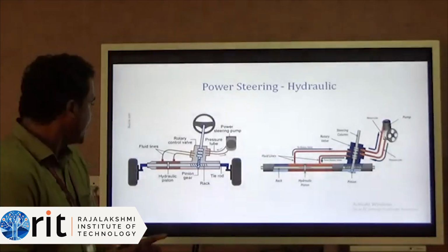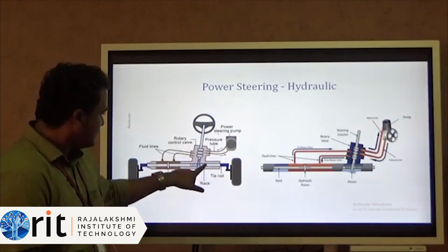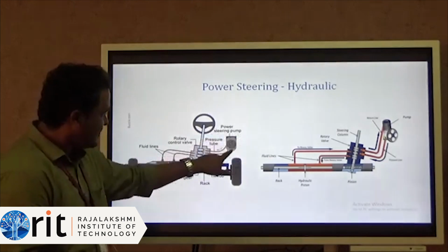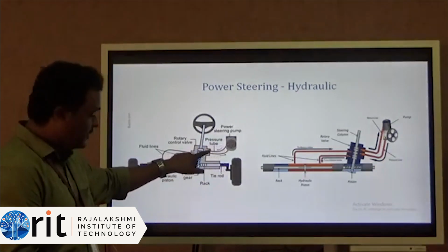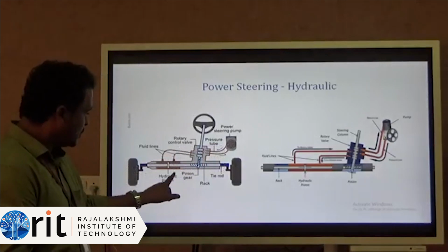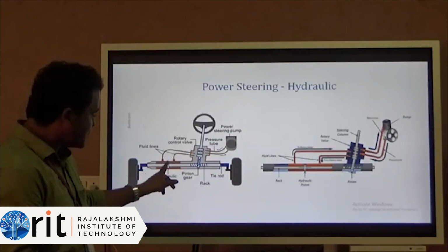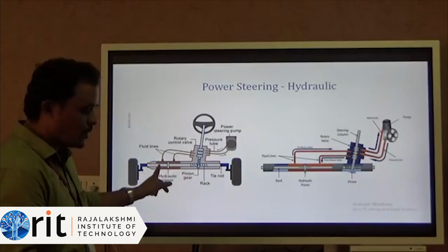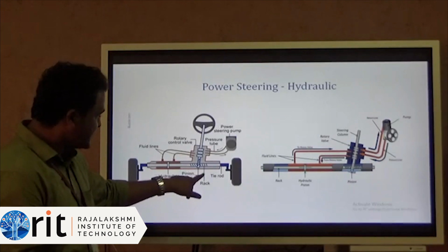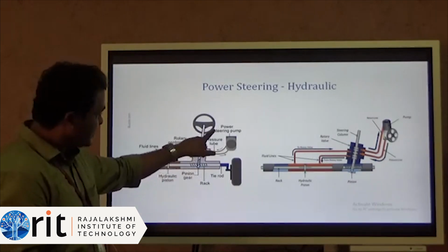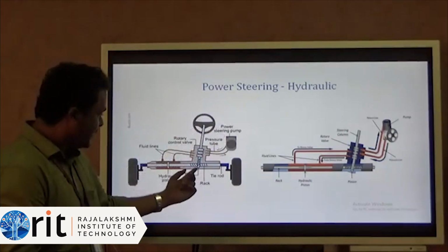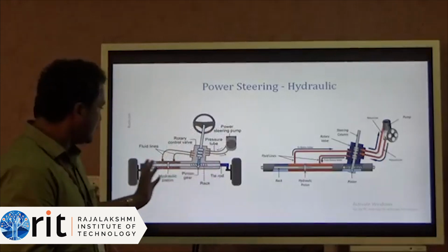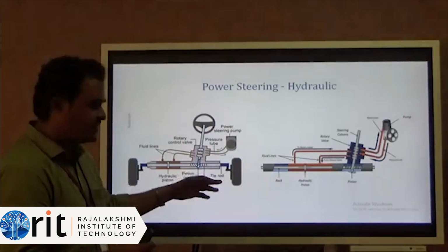and flexible. So here in the power steering system, this is the power pump unit. From the pump the fluid is taken here. From here the fluid is taken to the cylinder assembly. Here the hydraulic piston is actuated using the fluid in and out circuit. Initially this is the rack and pinion arrangement. When the driver is turns the wheel to the left or right, based on the connectivity, the rack and pinion gear will work. Based on that, the wheel alignment will change to left and right.